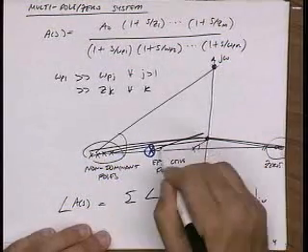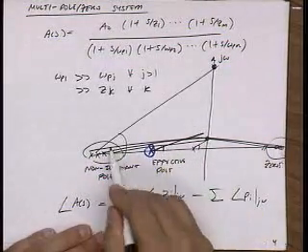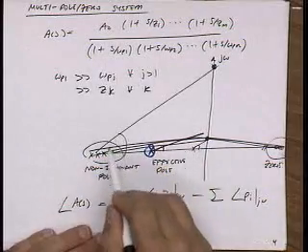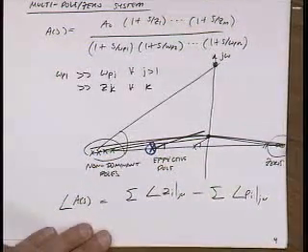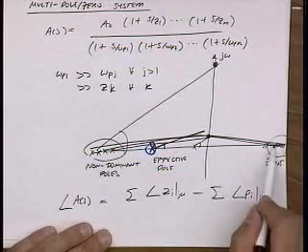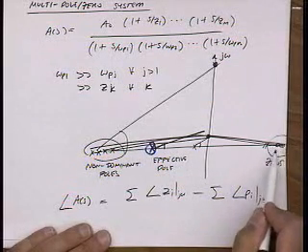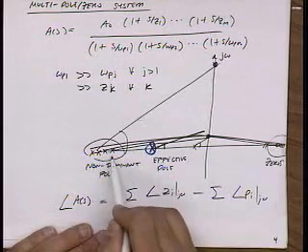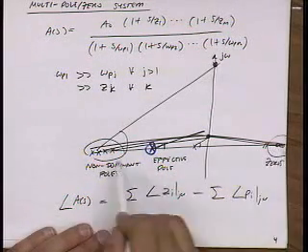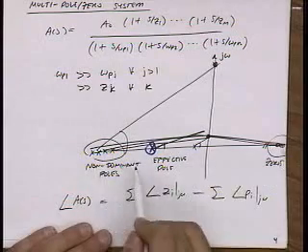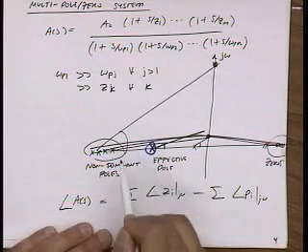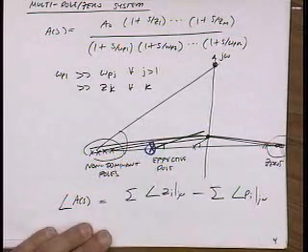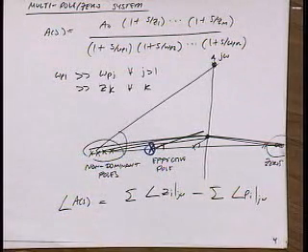That has an angle, which is the sum of all these angles, and has a magnitude, which is a product of all these magnitudes, right? And in fact, I can subtract out the angle of the zeros, right? Because the zeros are giving me positive angle, poles are giving me negative angle, so I can in fact subtract out the effect of these poles and zeros, and intuitively it seems clear that I can define an effective value of a pole. Yes, question?